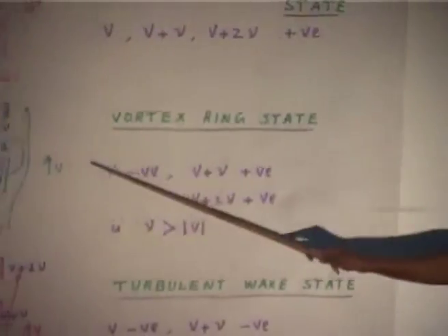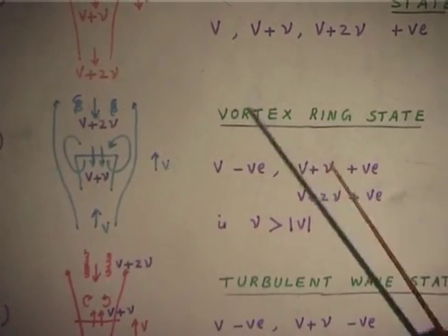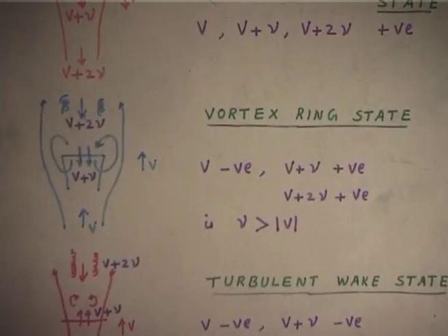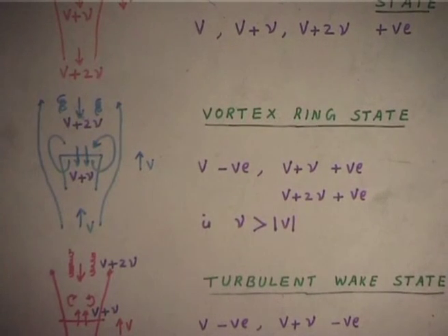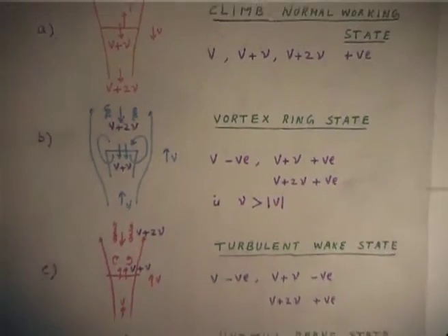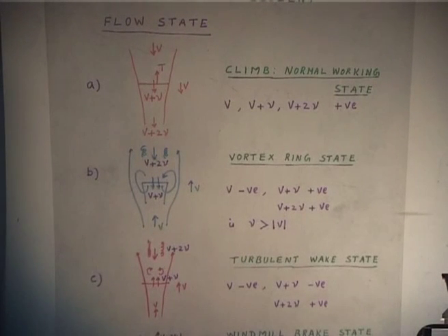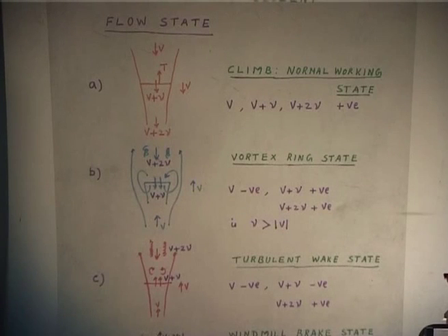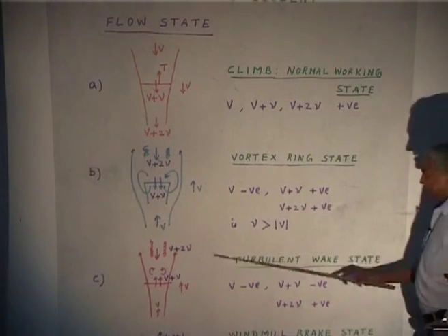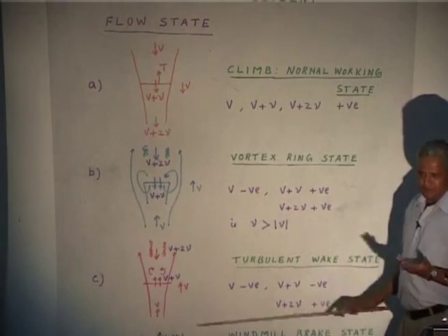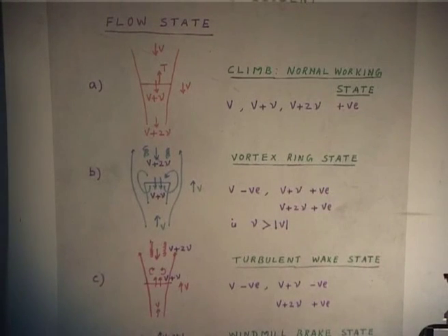That means this flow here and these are coming up, but if you look near, you have just started descending. That means the velocity V, capital V, is still small, because you have an inflow. If you are hovering, you will get a value of inflow in hover. You started descending and your descent velocity is less than the inflow. Okay. That means inflow is large, this is less, though I put the symbol V plus nu because V is actually opposite, nu is down, this is up, but nu is large.